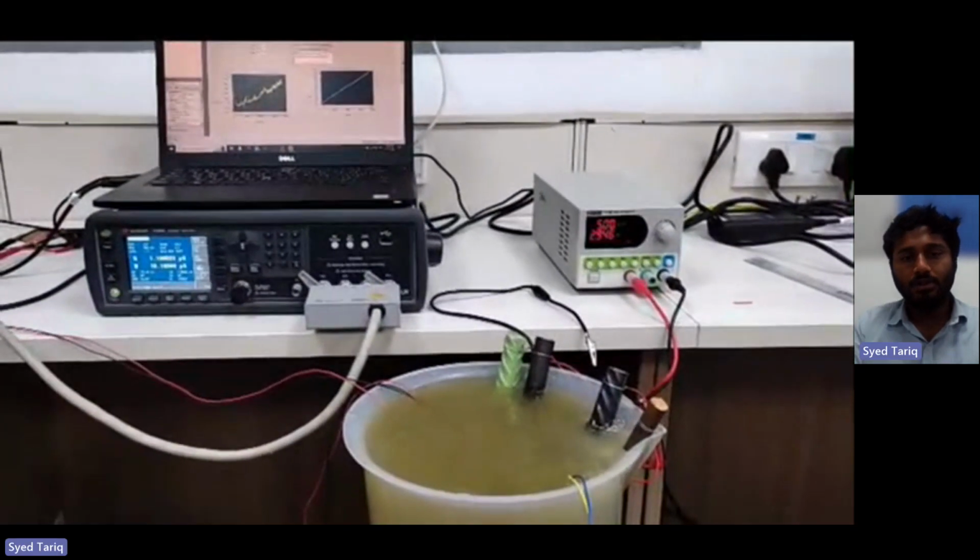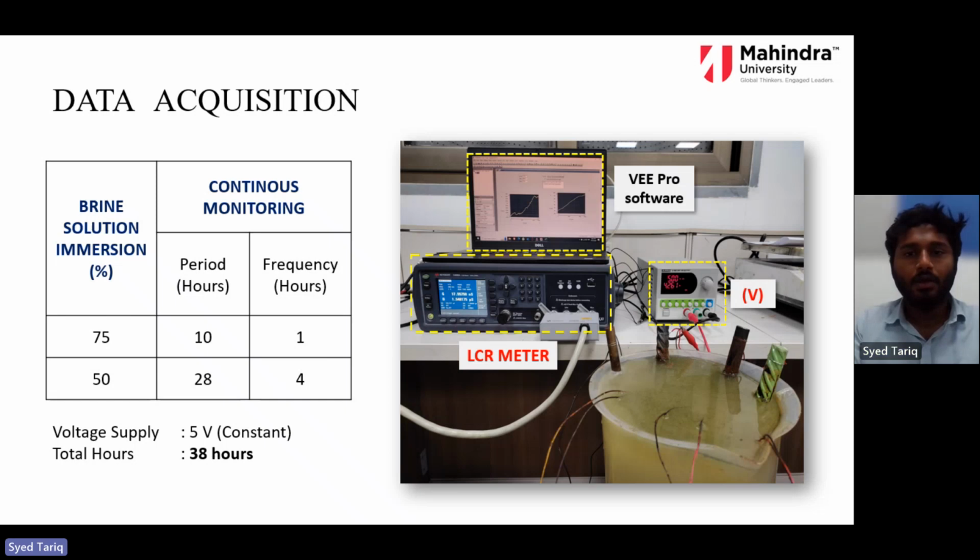As I was saying, for the actuator action to happen, piezoelectric sensors need to generate some electrical mechanical stresses. In order to create that mechanical stress in the form of vibration, we give a frequency of 30 kilohertz to 400 kilohertz with a step count of 100 kilohertz. And this is how the experimental setup goes.